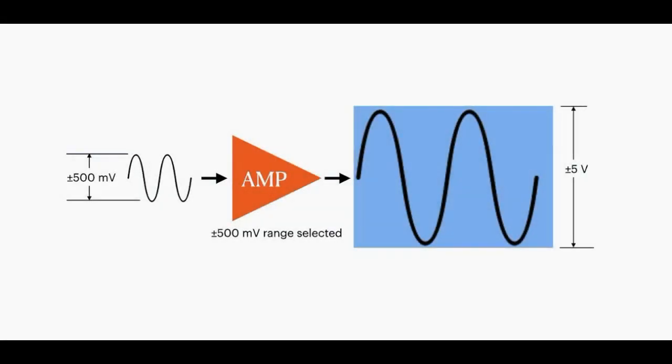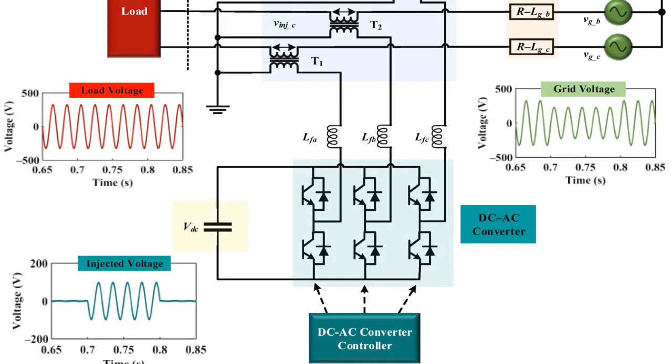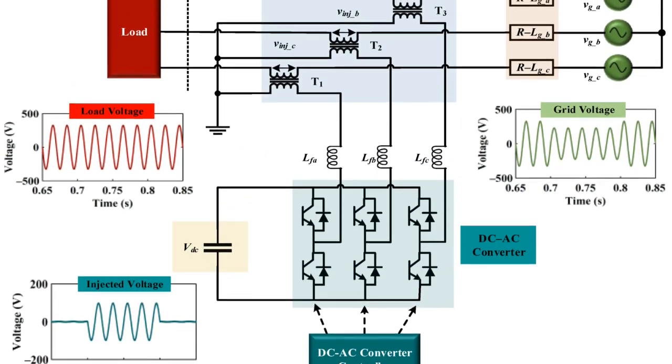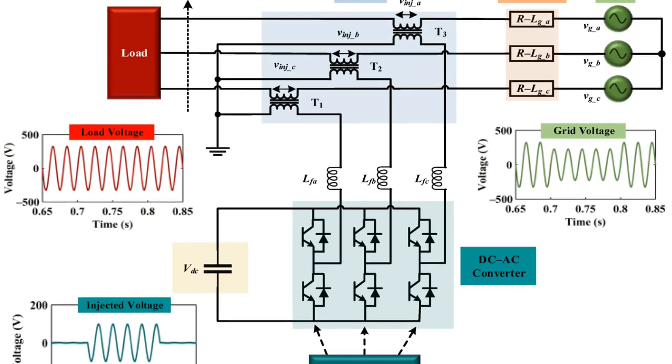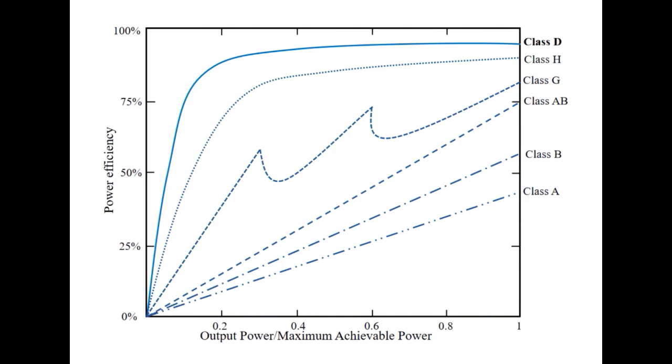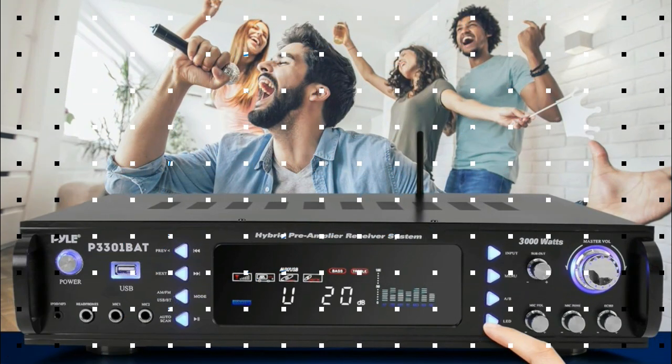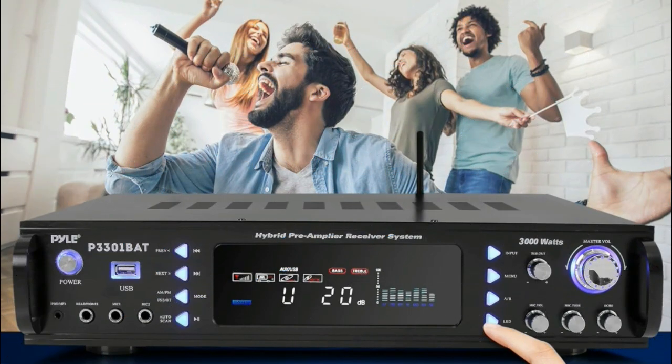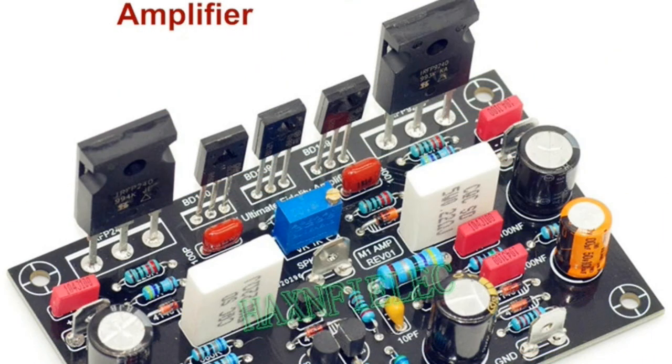This power is more than the input power of the amplifier. Power amplifiers convert the DC power of the power supply into an AC voltage signal for delivery to the load. Although the gain of these amplifiers is high, their efficiency for conversion from source to output signal is usually low. A perfect or ideal amplifier would give us a 100% efficiency rating, or at least that input power would be equal to the output power.